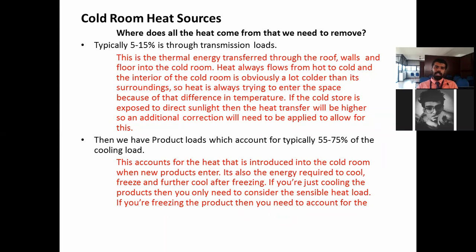Understood? So it has been found out that typically 5 to 15% is through the transmission load. What do you mean by transmission load? We have already studied. This is the thermal energy transferred through the roof, walls, and floor in the cold room. Heat always flows from hot to cold, as you know. And the interior of the cold room is obviously a lot colder than its surrounding. So heat is always trying to enter the space because of the difference in temperature.